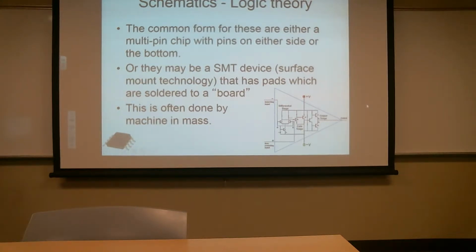But if I'm looking at the inverter, I take my oscilloscope, 2 different traces, and throw it on there. One signal should read the inverse of the other. If I'm not getting that, inputs, outputs, device in the middle, one of the 3 is bad, or the power supply.